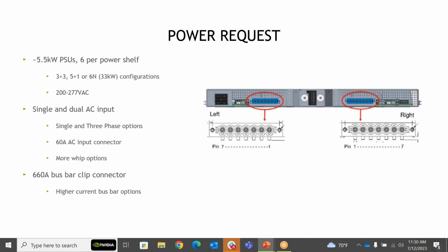Yeah, and that is one of the reasons why NVIDIA design clusters are N+N in power. In our designs, we don't see the 1.5 peak the same as anyone who would use like a 5+1 example. So that goes back to my comments about the AC to DC supplies, the bulk capacitance, and the smoothing effect that more supplies effectively have on the pulse profile presented to the utility. Okay. Yeah.